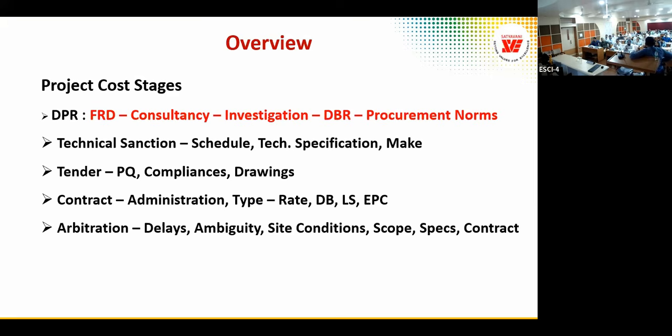Some departments have them. That means the rate analysis is sacrosanct in percentage tenders. Once we fix the rate, the percentage quoted has to be applied on the rate given, and there is no change in that. Next is the arbitration.